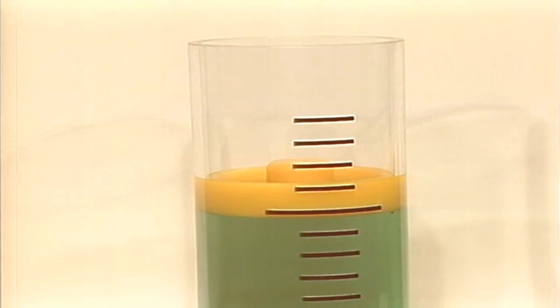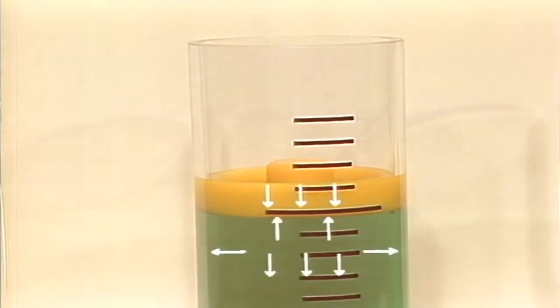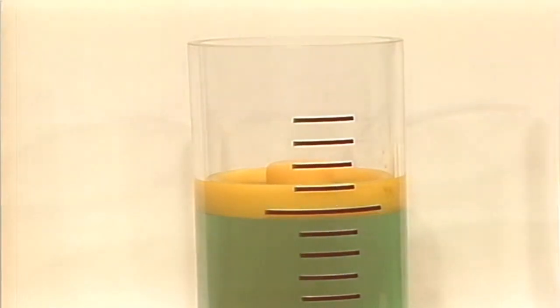Let's look at the basic principles of the hydraulic system, because this controls everything that happens in the hydraulic brake systems. Under normal pressures, liquid cannot be compressed. This heavy weight, for example, cannot press the liquid down beyond its original level. It is, however, putting force on the liquid. This force acts in all directions, putting pressure on the weight itself, and on the walls and floor of the container. The pressure is the same at all points.